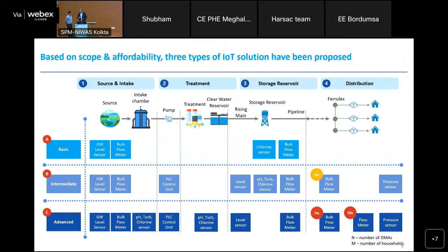In your experience, how do we solve for this kind of problem? This is a very practical problem. The whole system shuts down if we don't have a network. But LoRa, you have to use only for the first mile, right? From the sensors till the gateway. From the gateway, we have to depend on GSM.